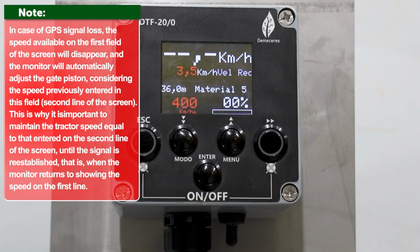Note: in case of GPS signal loss, the speed available on the first field of the screen will disappear, and the monitor will automatically adjust the gate piston, considering the speed previously entered in this field, second line of the screen. This is why it is important to maintain the tractor speed equal to that entered on the second line of the screen, until the signal is re-established, that is, when the monitor returns to showing the speed on the first line.